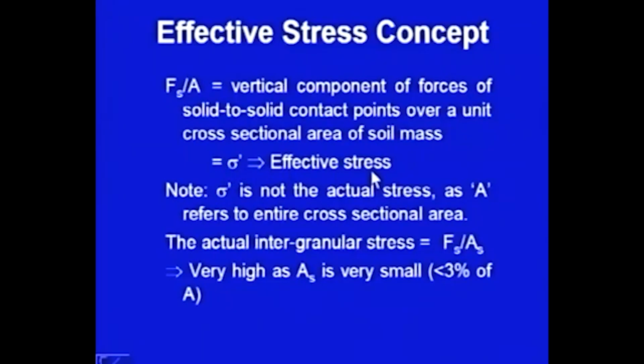Please note here that A is the total area, it is not the contact area. So, this sigma dash is equal to Fs upon A. The actual intergranular stress, if you are interested in finding it out, should be equal to Fs divided by the actual contact area As.